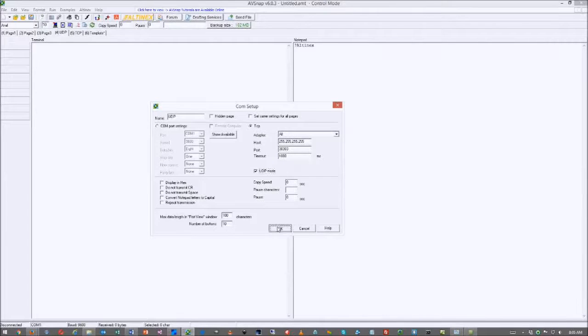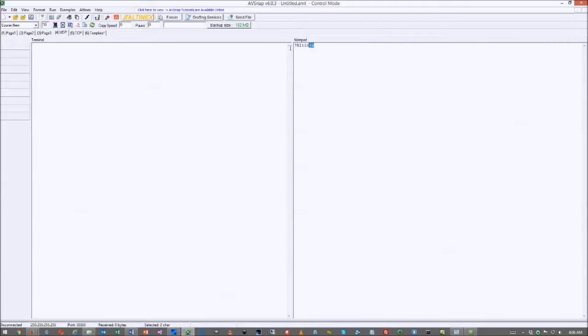So that's my UDP. So if I want to know what's on the line, I just type in question mark UDP. Now notice when I click on the bottom left corner where it says disconnected, if I click, it says connected. And the reason is because UDP mode is a transmit only mode or broadcast only mode. It's almost like RS-232. You're sending the command, you don't care who's on the other side, you don't care who's listening, you're just sending the command out, and the appropriate devices that have the right port will respond to you. So there's my 3 pages.